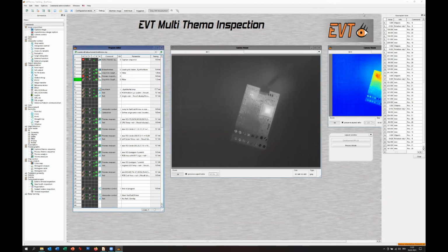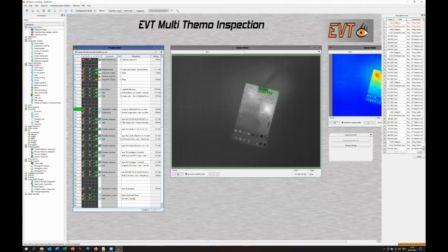Then we run it to this position, and you see here we have one match, because we have only one object which we searched. And of course, the object has a rotation related to the trained one of 19 degrees. So this is the information which all the other tools need to know. Where is the part and what is the rotation? Of course, the position information is also in the other registers. You don't have to think about it. It's implicitly stored.